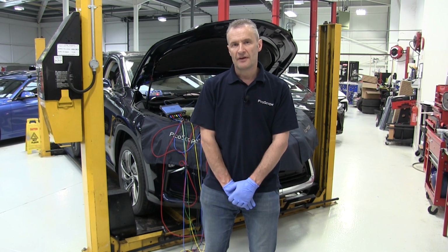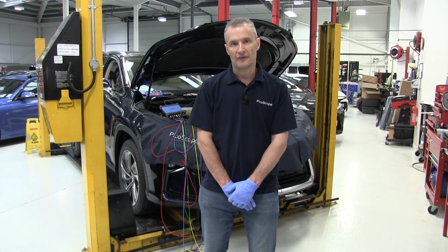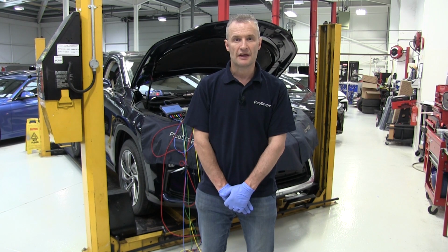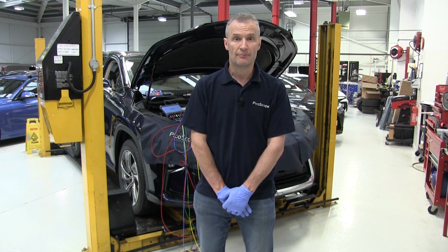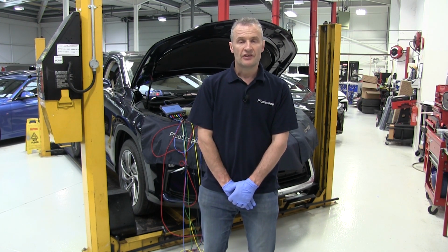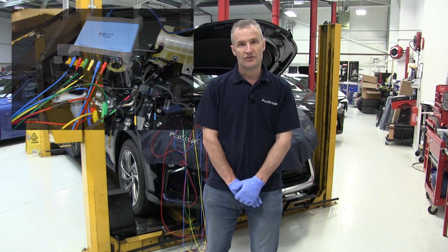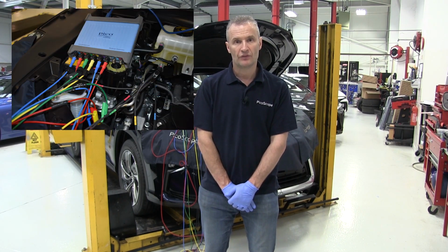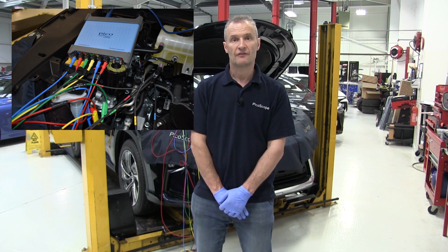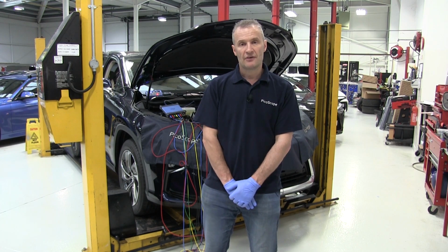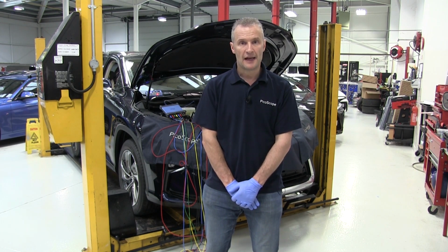But using the dynamic valve timing check, so that's all cams against crank and an ignition signal, we were able to plot the relationship between cam and crank, and measure the deviation. So as we've got here, you see we're connected. We're using 6 channels because we need 4 for cam, 1 for crank, and then an ignition trigger for number 1 cylinder. The vehicle is now repaired, so this is our post-repair capture.